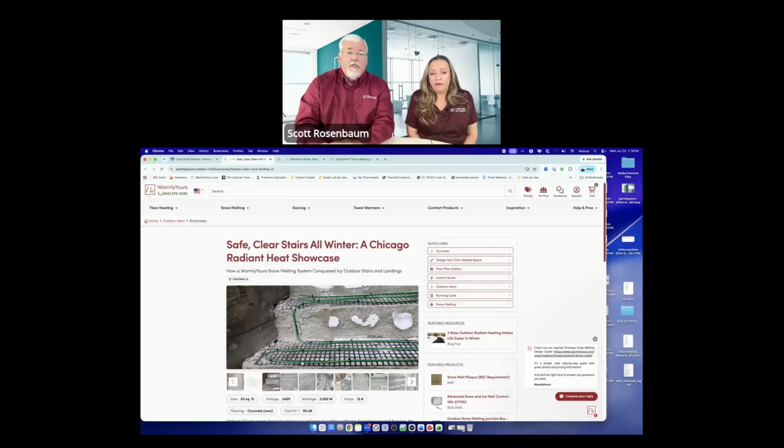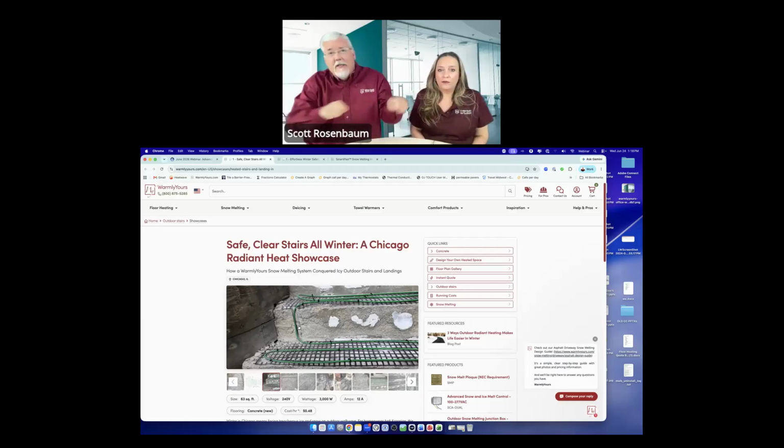Now, when you're doing these steps, there's a couple ways to do this. Many times you can run the cable down and make a softer loop, but you can see here where we've actually trenched into the concrete. You're creating a spot for that cable to go down in front, because when you're putting something on the riser, or if you're putting limestone caps, the people putting the limestone caps want to put the mortar down, and then they want to move the caps down like this.